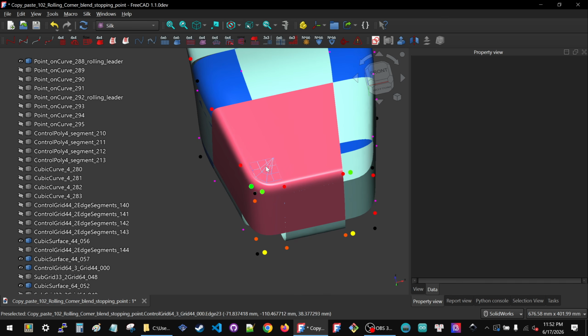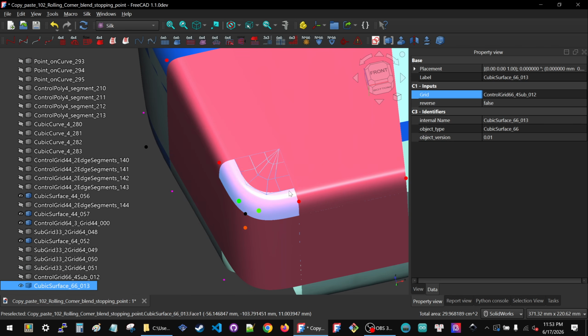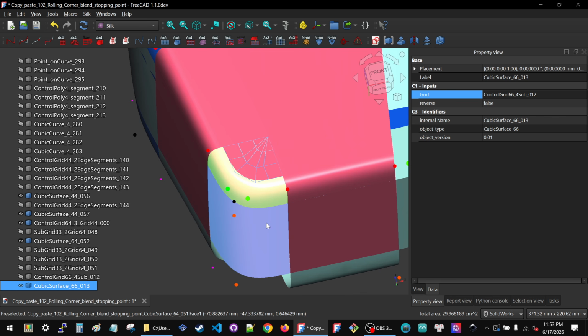But when we replace this face with just a filling surface, it's going to have a really easy time, because this curve that it has to incorporate along with these two edges is awfully close to being on the surface itself. So it will be able to create the surface really easy, and then when it goes to make the trimming curve, it's already on the surface, so I think you get a really good result.